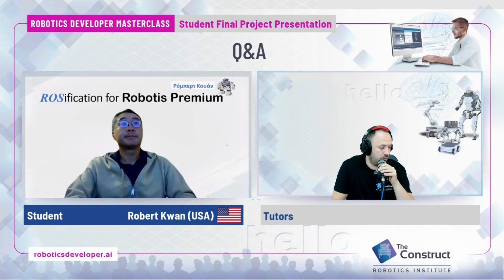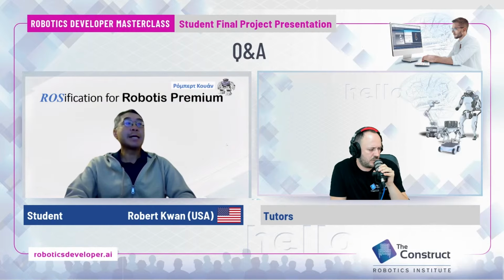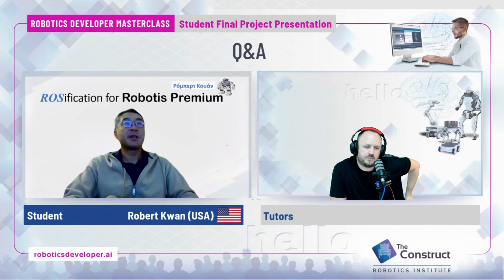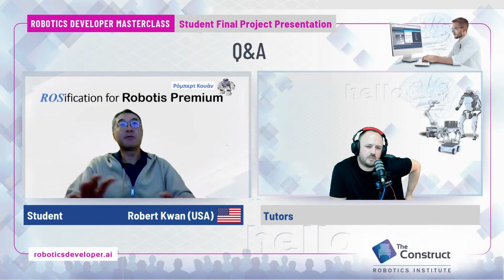The question is what communication protocol the U2D2 uses. Is it serial? It's basically serial, but they have their own format called DXL protocol 1.0, which is actually just 5 bytes with some header information. It is just serial, like UART, but in their own format. Nothing really magic.